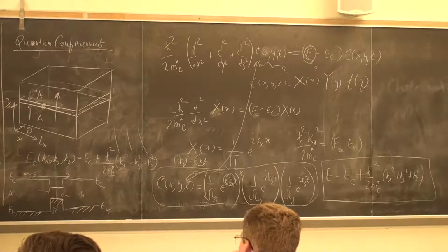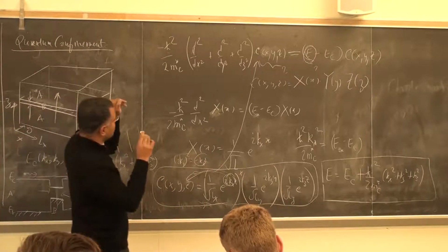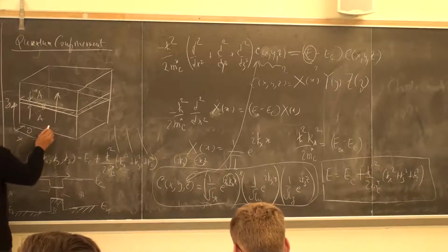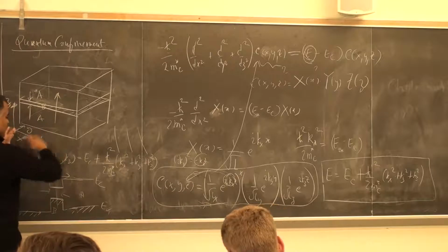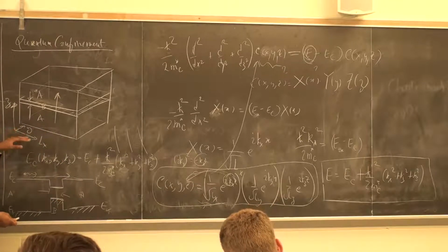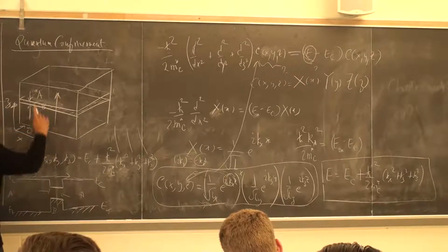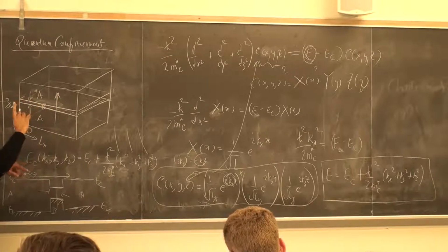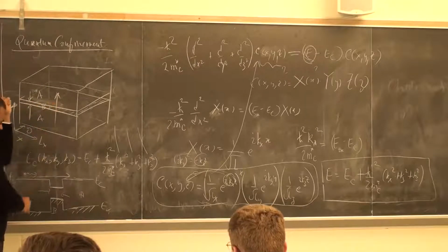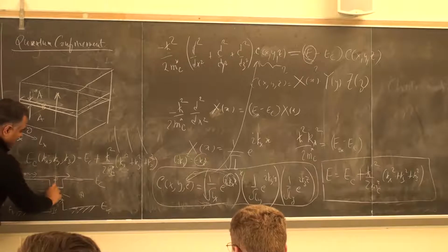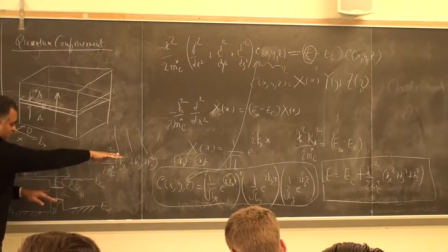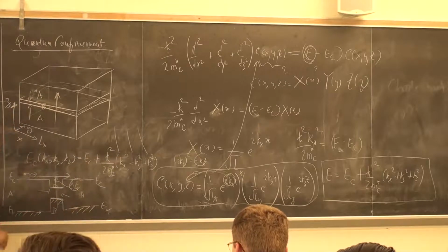Now if you look at this problem, every problem of this nature is where electrons are still free to move in the x and y plane. There are no potential barriers in the xy plane. The only thing that's changing is if the electron has any momentum in the z direction, it experiences this change, delta EC, which is what we call the band offset, the conduction band of A minus the conduction band of B. And this is fixed by materials.